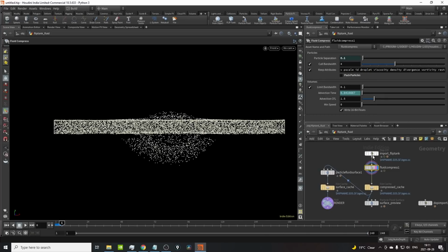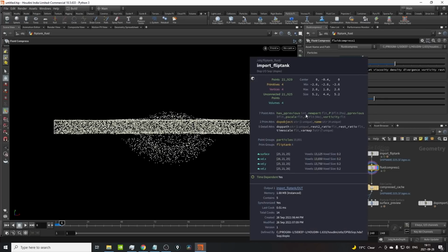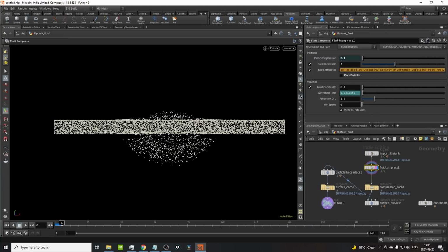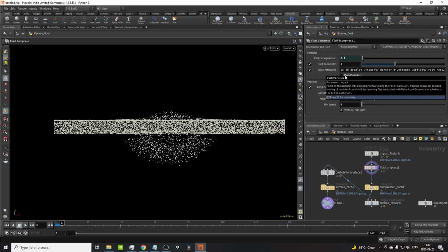But if you keep 5, maybe later on when we get into some custom stuff, maybe 20 additional attributes, each one of them per particle, all of a sudden you have 22,000 additional attributes times 5. That's a relatively low resolution simulation, right? So this data set stacks up really quickly. So Houdini here by default deletes everything but the attributes in here, which means if you do custom attributes, you have to make sure to add your attributes in here if you want to keep them outside of the simulation, right?